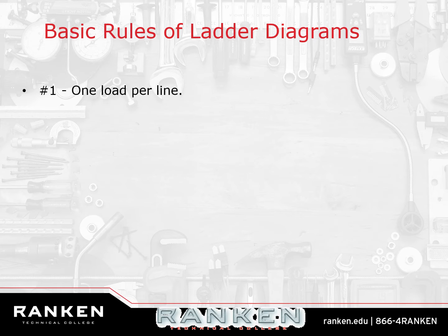Voltage adds in series. So if I put 2 loads in series in a 24 volt system, each load, if they're equal in resistance, is going to get half of the voltage. Can't have that. It needs 24 volts to run. So I can only have one load per line because I need the full amount of voltage going to the load.